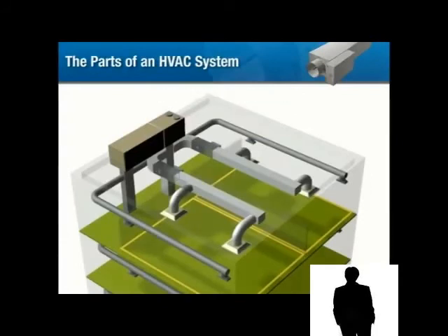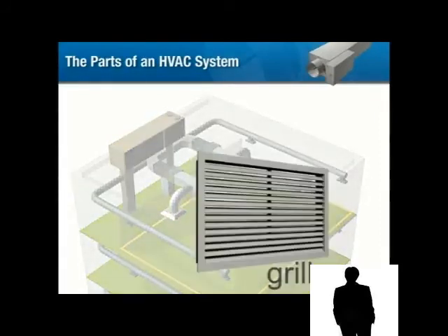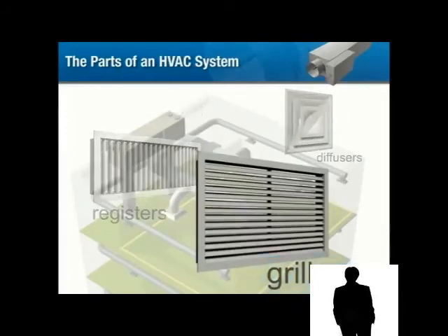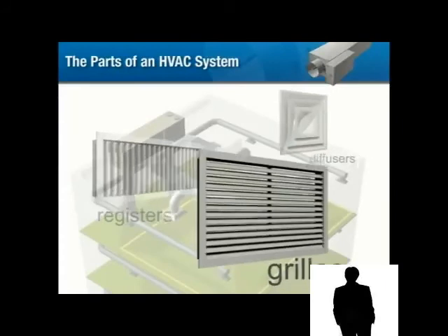Ultimately, the test of an HVAC system lies in its ability to deliver conditioned air to the occupant. Air from the ductwork enters the occupied space through grilles, registers, or diffusers, often called GRDs. The term grille is commonly applied to any air outlet or intake that consists of a square or rectangular face and neck and whose facial appearance is made up of louvers, which may be used to deflect the air.